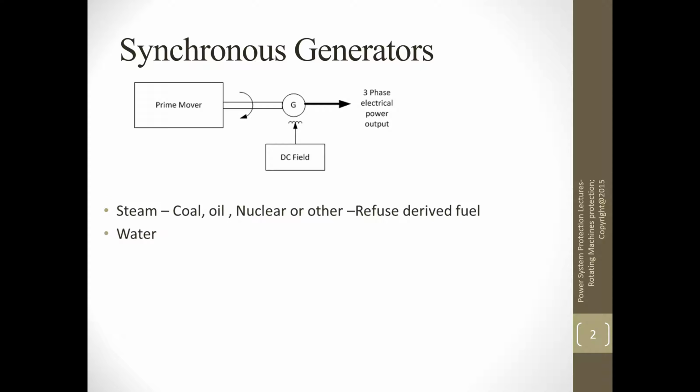We also need DC field excitation to keep the voltage up at a nominal value, and this DC excitation provides the reactive power that is generated by the machine.